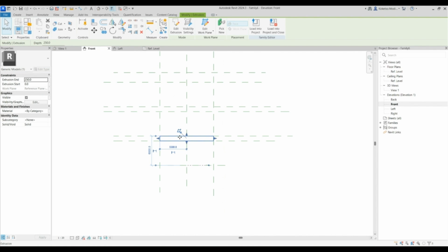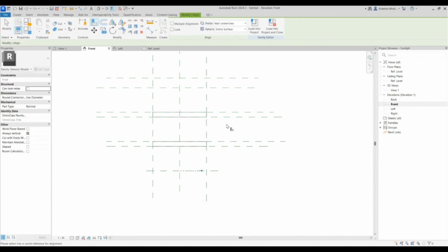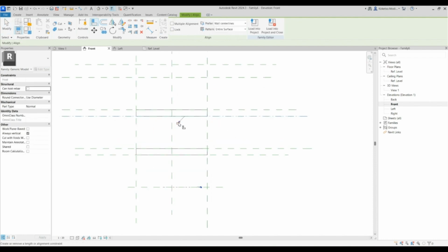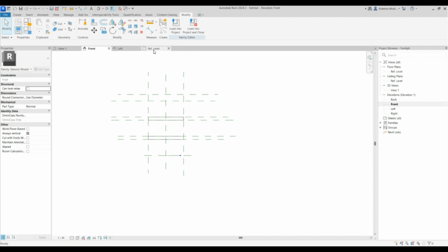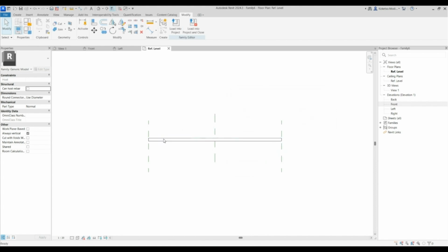Say finish edit mode, and I'm just gonna copy this towards this one, and then I'm gonna leave it like that. So let's just, side so that when you apply your parameters, these can be affected. So if I go to the front elevation, I'm gonna set this to VR unlimited. Set this offset to 25,000 millimeters, apply, and then OK.